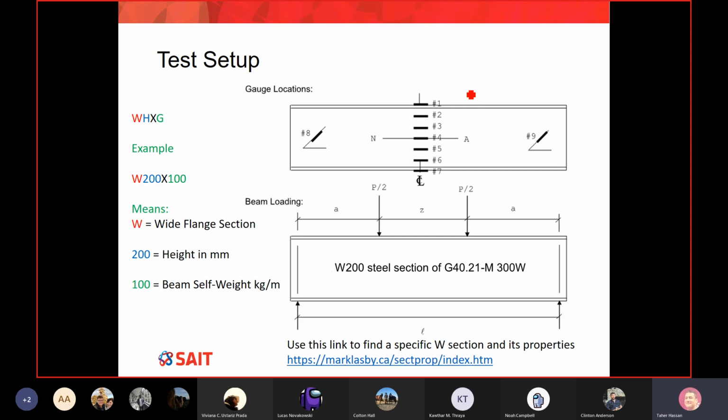For example, bridges. Bridges have long spans and the loads are high, and the sections that we get from the mill are not really enough for us. And that's why for bridges, we simply build up our section from plates. However, in general, in most cases in building and other construction, we use standard sections. So I'm going to take you through the process a little bit, not very deep, because you will have a deeper discussion in other classes.